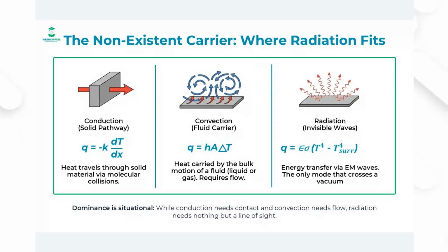Conduction is the solid pathway. It relies on molecular collisions, direct physical contact, and as the equation states here, heat transfer is equal to negative k dT by dx. This is strictly limited by material properties, specifically thermal conductivity.